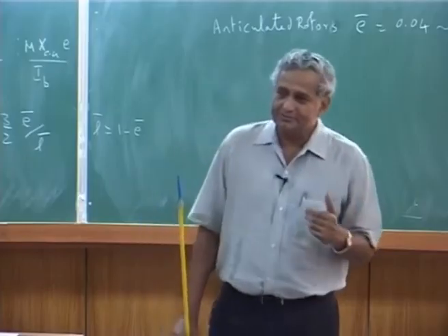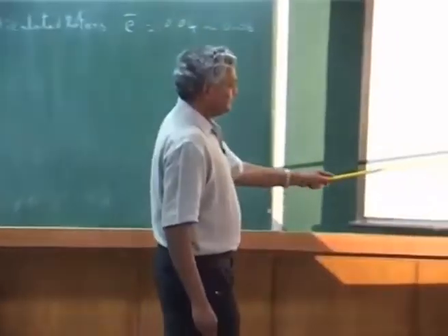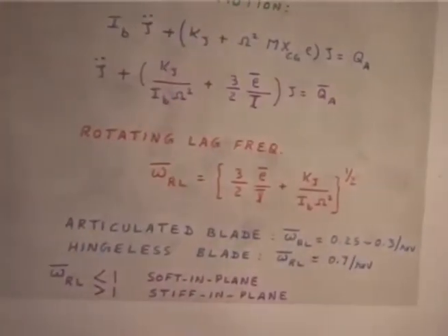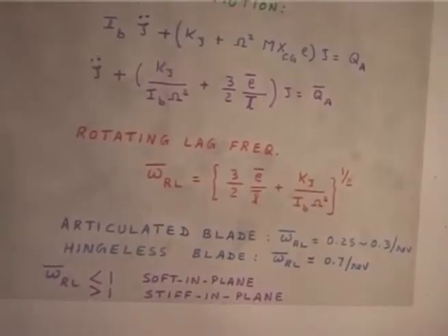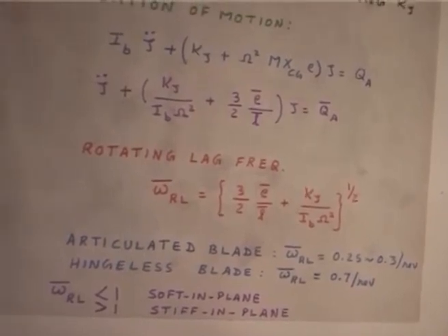Tail rotor systems, by design you try to have stiff in plane and then keep the frequency far away, and then you do not have a damper, absolutely no problem, but loads will be high, but you live with it, because tail rotor loads are not very high, so it is okay. So, you see, in the design and selection of rotors, the frequency placement plays a major role, and depending on where you place it, you have to add an additional system, because the system can go unstable. So, you say, okay, I have to put one more damper.